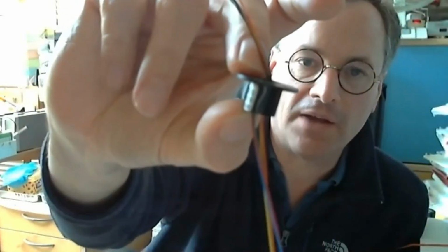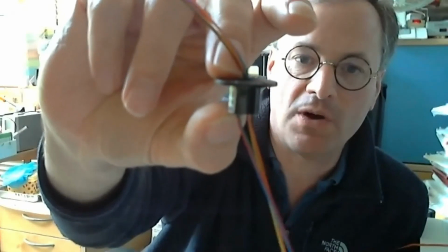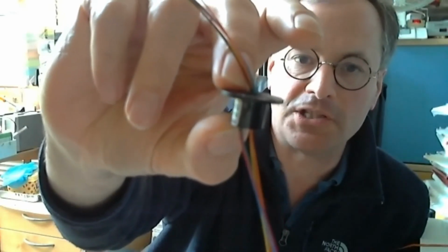Yeah, if you look at the size of the thing, it is so small that with the 6 wires going in and 6 wires going out, the actual area within which the wires are in any proximity to each other is tiny. So I think the chance of anything happening is very small. But it's just a lovely little thing. It's a couple of pounds on eBay. You can also fix it, if you do get crosstalk, just put a couple of snubbers on. We just fitted snubbers to the DCC, and that fixed it.